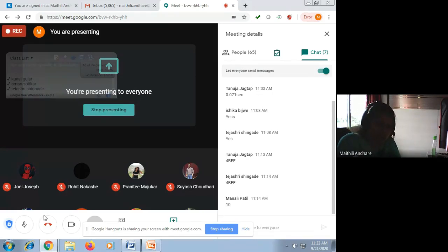So why clear the timer overflow flag? For the next iteration. If you want a continuous square wave, you can use the SJMP instruction. Otherwise, you can directly end the code. That is up to you, that is up to the problem statement. Somewhat minor changes the user has to make according to the problem statement.